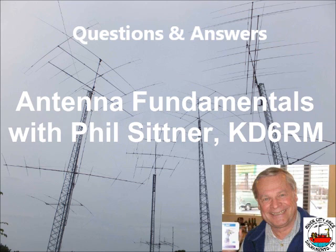Yes, Paul? But all of the matching devices are at the expense of power output, right? No. The most efficient method of getting all the power possible to your antenna is to use a feed line that matches your transmitter output impedance, and at the antenna, do the matching.